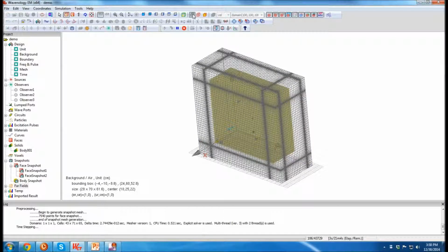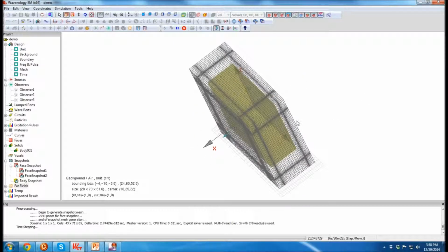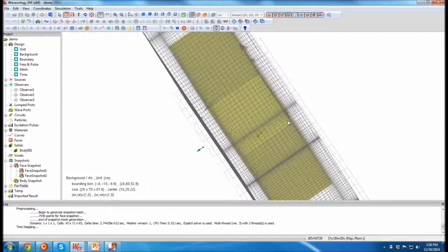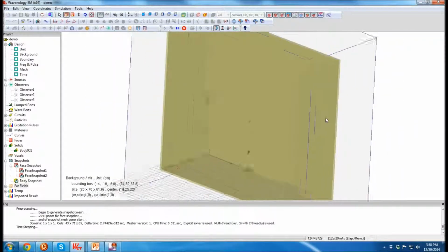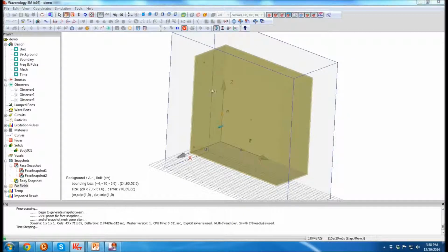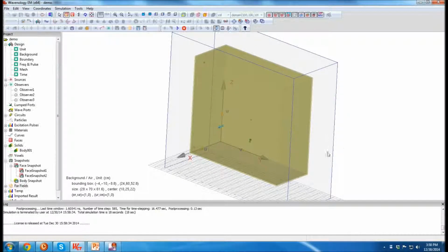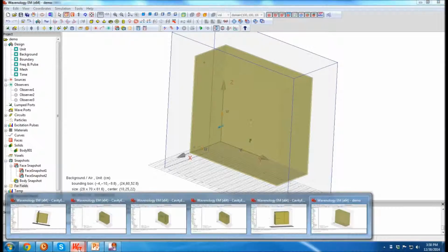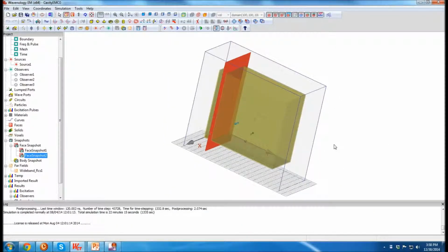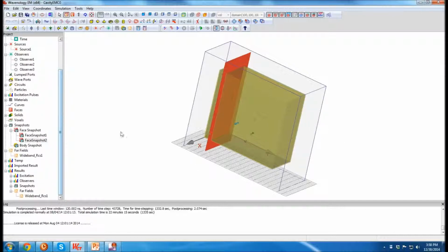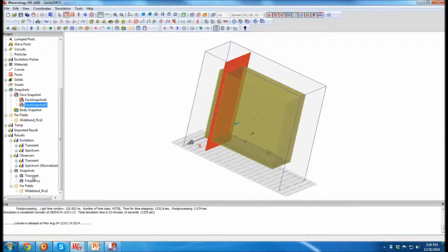Okay. If you want to, you can also check the mesh. As you can see, the detailed thickness can be captured with the FDTD mesh. Right. So this simulation is going to take a while. I've already pre-simulated everything, so we just directly load the result and check how this PC box is radiating without any features added. So after the simulation, you can see the results showing everything here: excitation pulses and also the